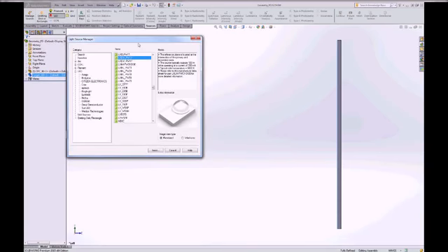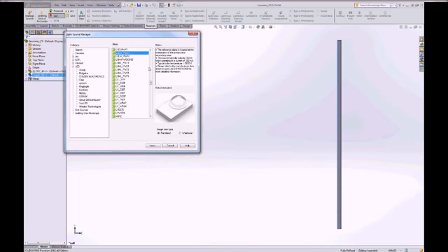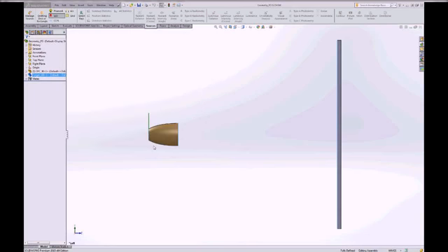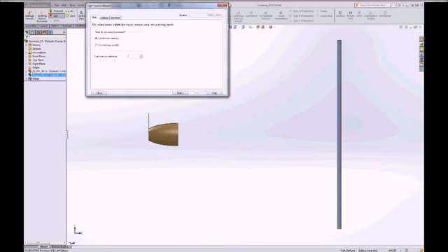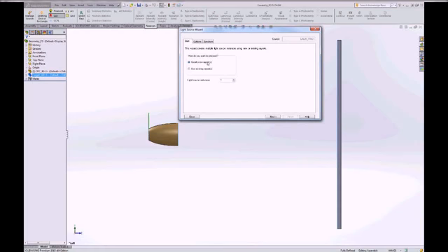It will be inserted when we go through the process at the origin, and then we'd need to go through and mate it. So if I want to insert it, I'm going to get a little pop-up, and we'll create a new ray set. If you happen to have a ray set file from the manufacturer's website, you could instead insert that as well. If you want multiple LEDs, you can insert multiple LEDs at the same time.